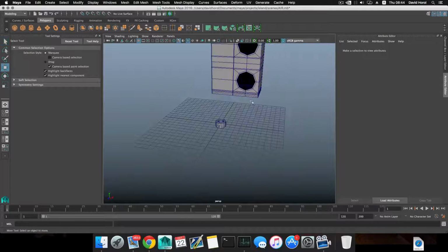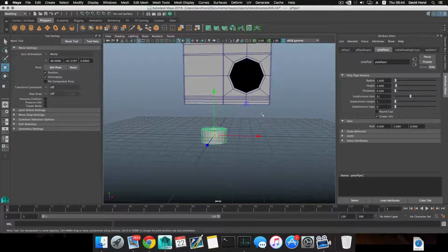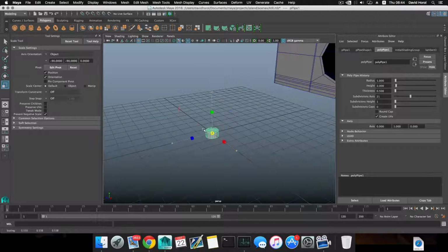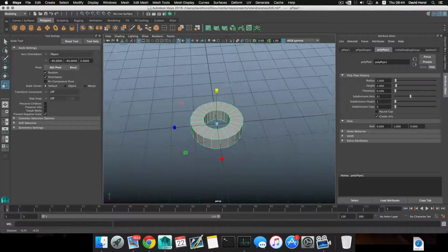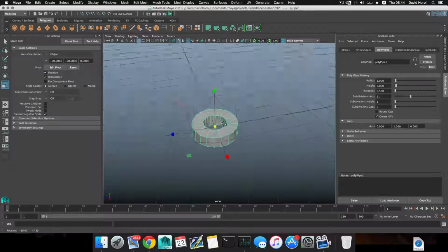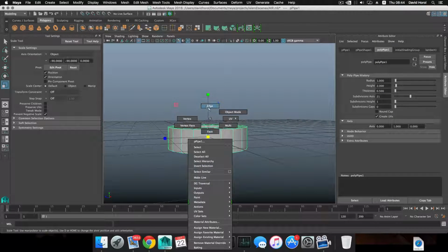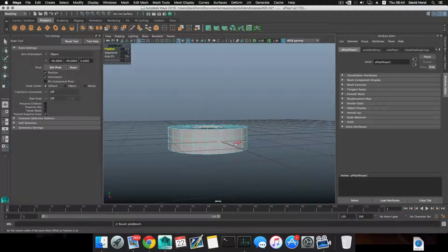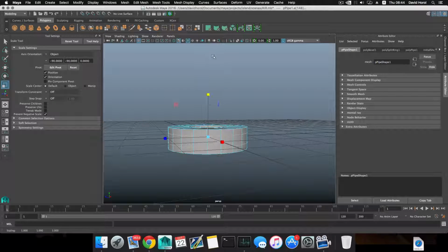All I want to do is somewhat scale this to a scale that is reasonable to be in the center here, not to take too much from what I already have there, and just use it as a fan for these holes there. So I'm going to right click, choose edge, grab this edge, Edge Ring Utilities, To Edge Ring and Split, shift right click, bevel it, click on this one, shift double click on this one, switch to the scale tool.